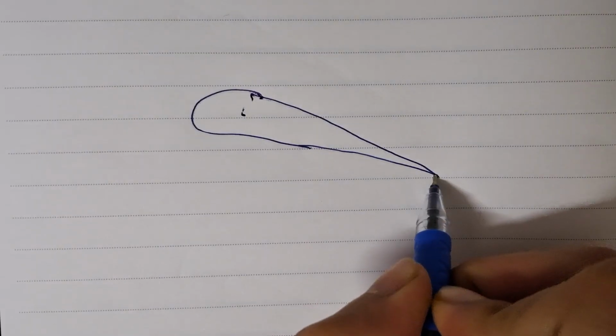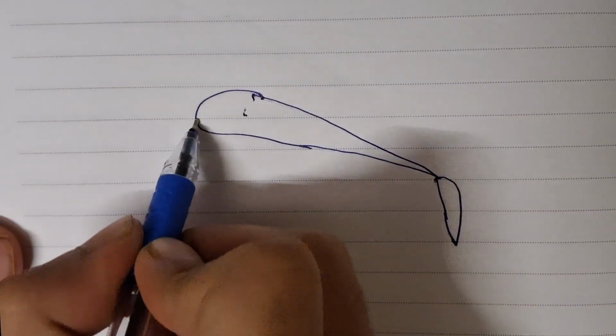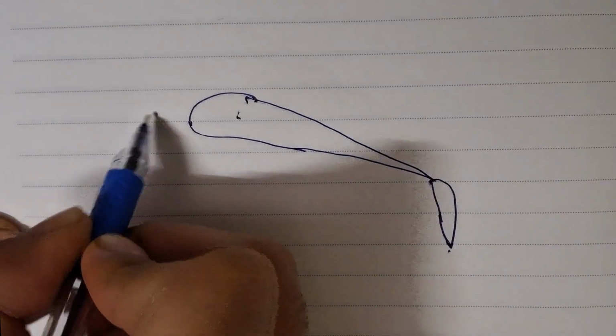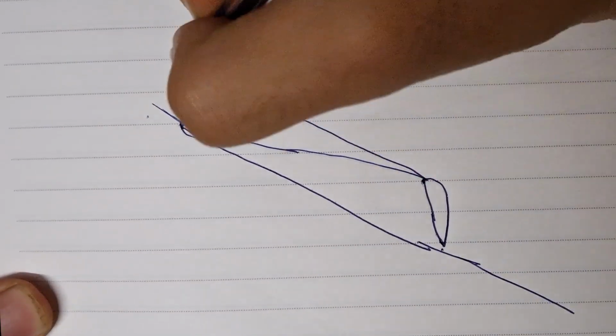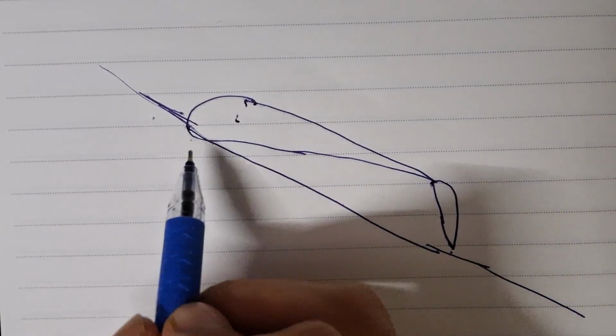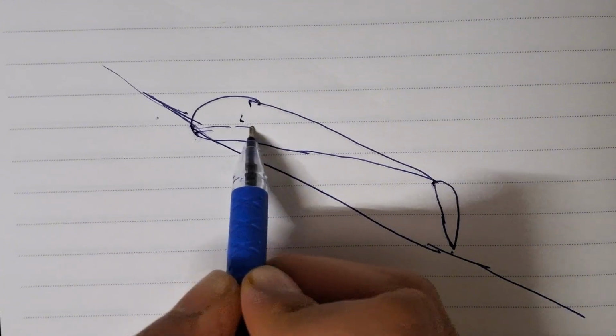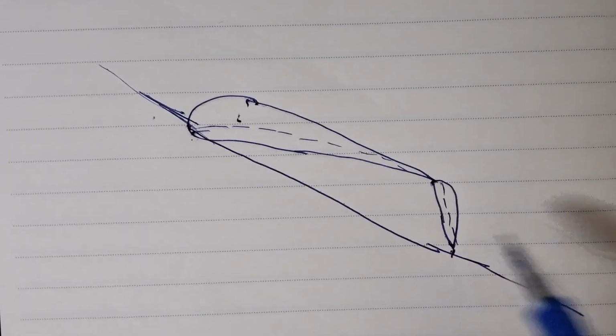That we'll see now. So now, for example, if I have an aerofoil like this and my control surface is deflected, for example, downwards, right? So this is my control surface. And what will be my chord line? Again, leading edge to trailing edge, a straight line. So something like this would be what? My chord line, right? And what will be my camber line? So camber line is a curved line which is dividing upper and lower parts in equal halves. So the camber line would be going something like this, right? Dividing it into equal halves, right? So it will be like this.